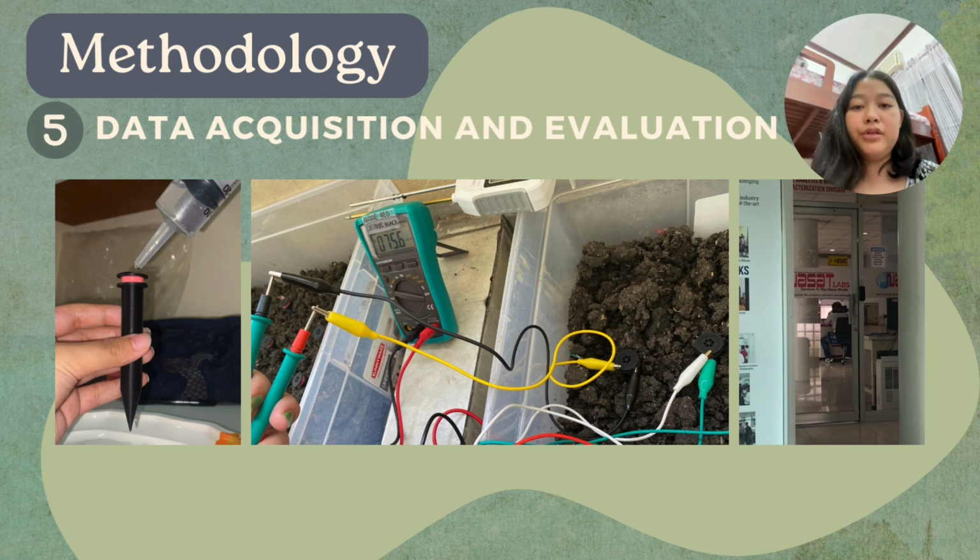Throughout the 24-day operation period, the electrodes were installed in the vermiculture setup and regularly watered to maintain adequate moisture levels and ensure active microbial growth. Voltage and current data were continuously monitored using a multimeter and alligator clips to track the system's performance. Lastly, 3 anode samples were submitted to NASA labs for scanning electron microscopy, imaging, and analysis to gain detailed information about the electrode outer surfaces.